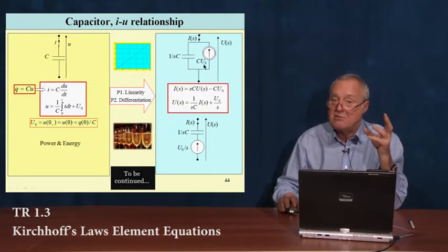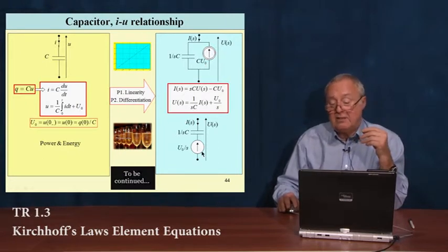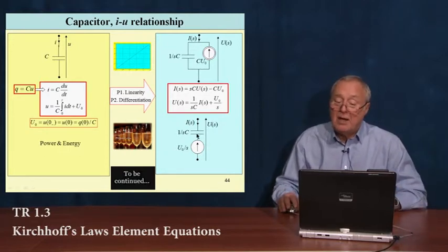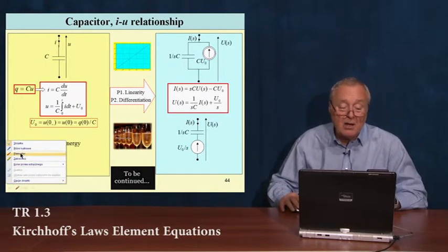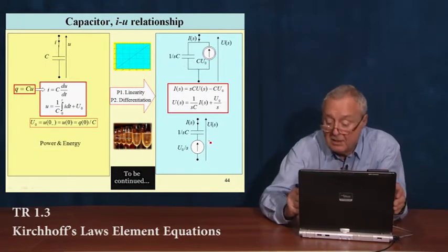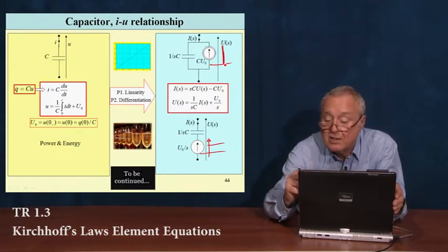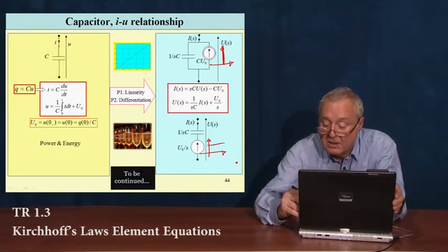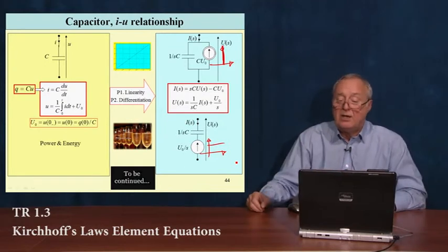The capacitor initial condition is the voltage across the capacitor. And this is the parallel equivalent circuit. This is the series equivalent circuit. Capacitor without initial condition, and here initial condition is taken into account as a step. This corresponds to a step in time domain. This corresponds to an impulse in Laplace domain. In time domain. In Laplace domain it is C U sub 0.